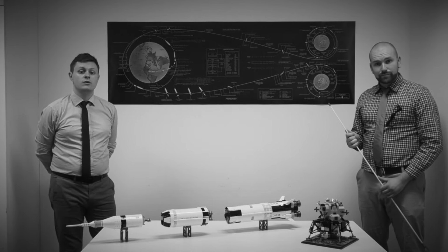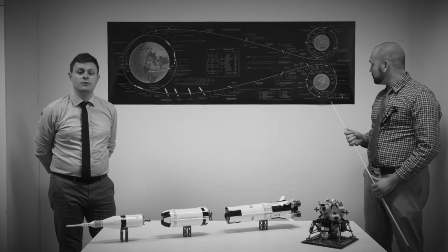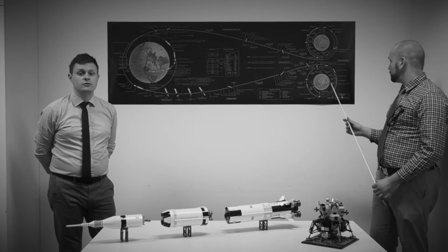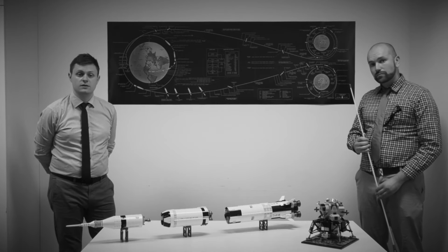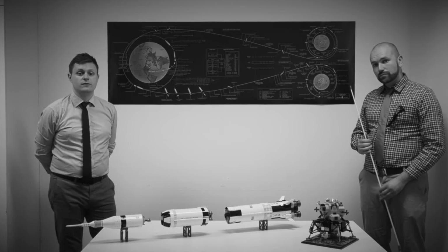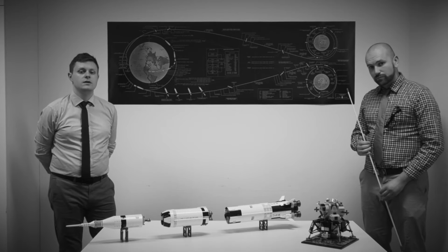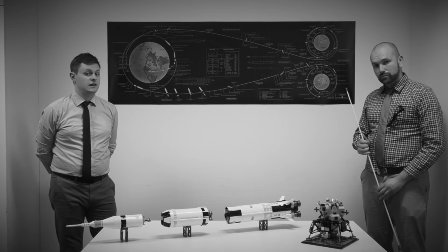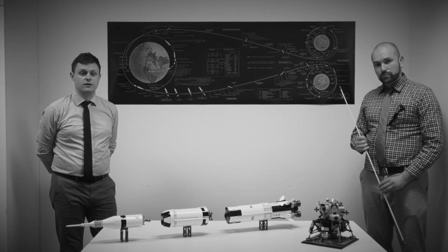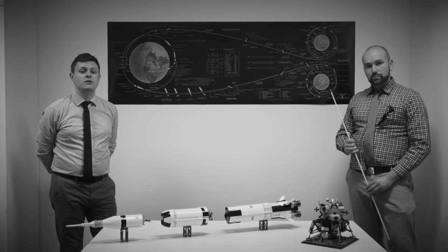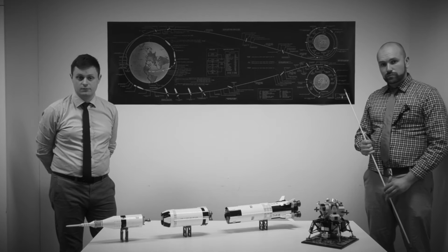Two astronauts board the lunar module and decouple from the command module. The lunar module has its own AGC with separate programs for this task. Descent down to the surface is split into 3 phases: braking, approach, and landing. The crew starts Program 63 for the braking phase. For now, it's just about slowing down from orbital speeds.